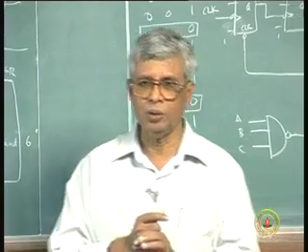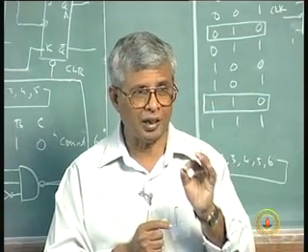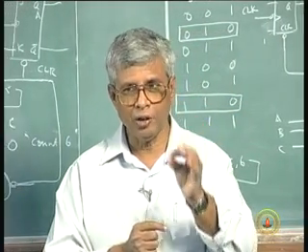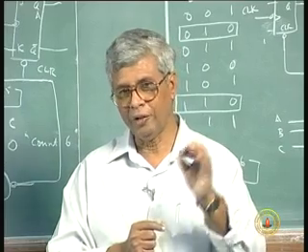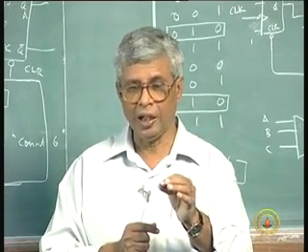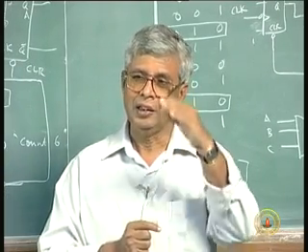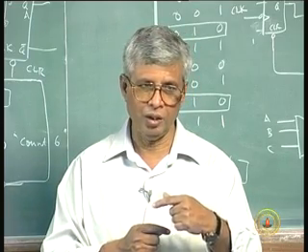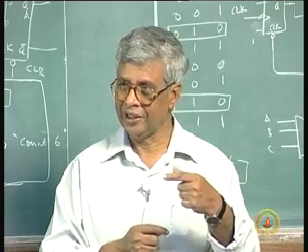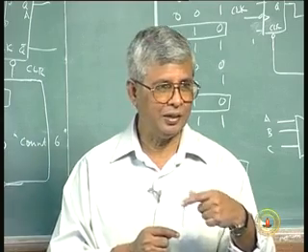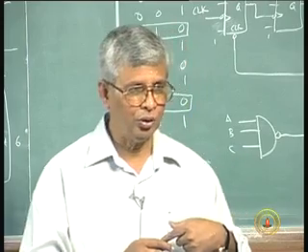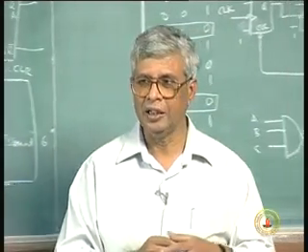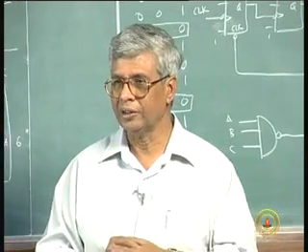So the crystal frequency clock has to be brought down, from very very high. You do several divisions to make it one cycle per second to count seconds, then divide by 60, you get 1 cycle per minute, divide by 60 again to make it 1 hour.